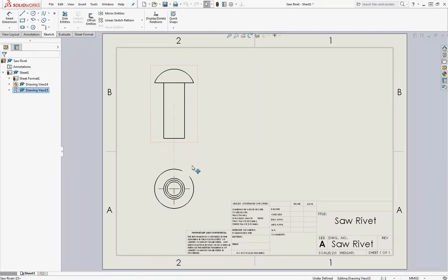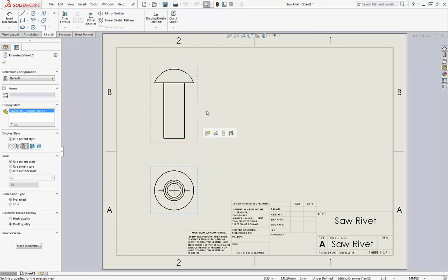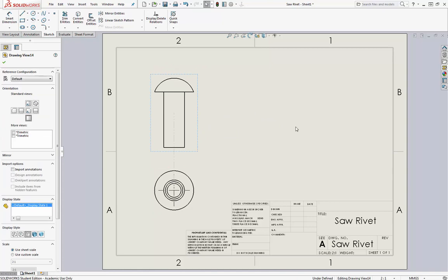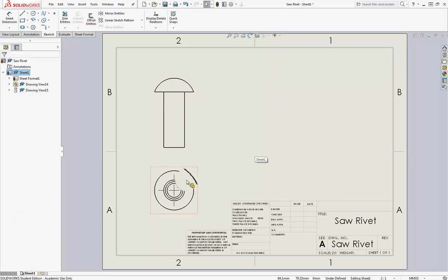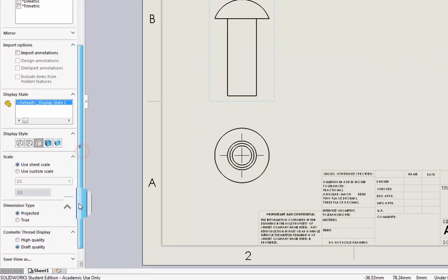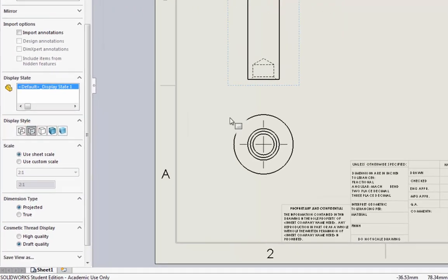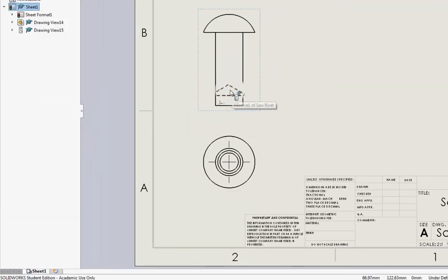We're back here, and now I've got a little more space for this particular view, and I'm going to make another view that's going to help us out here. I can't really see what's going on inside here very well, and I could make this, if I wanted to, a view with hidden lines. See? And now I've got these details in here in a hidden fashion, but that's not good. You want to define things with clearly identified solid lines.